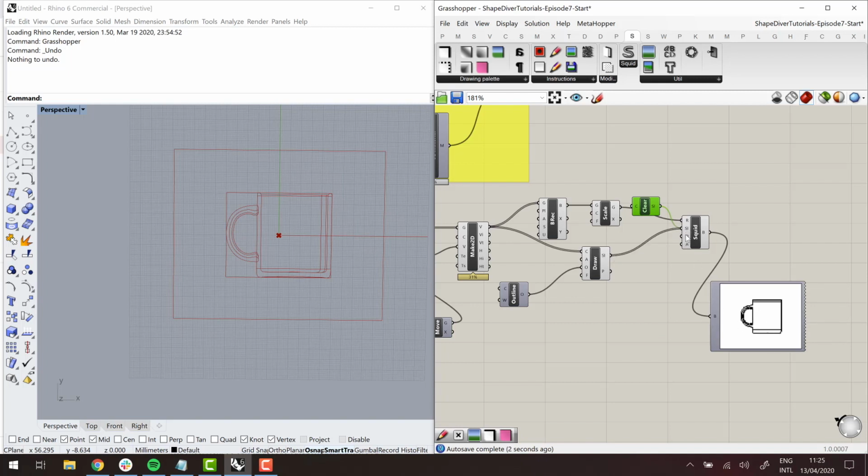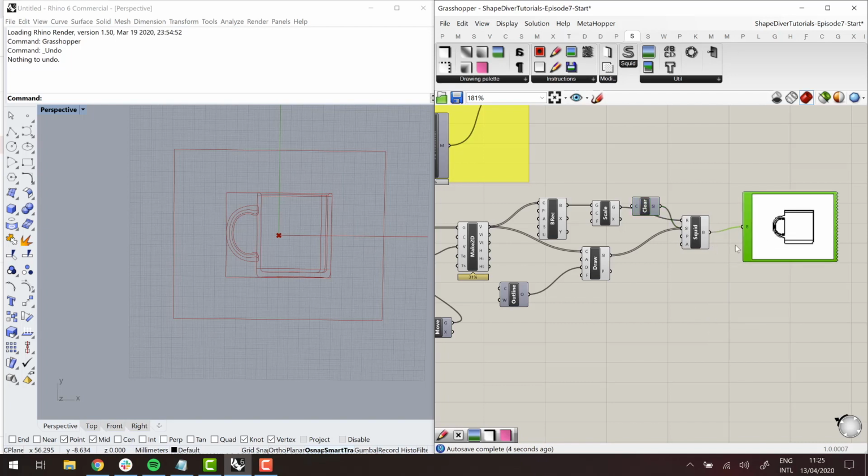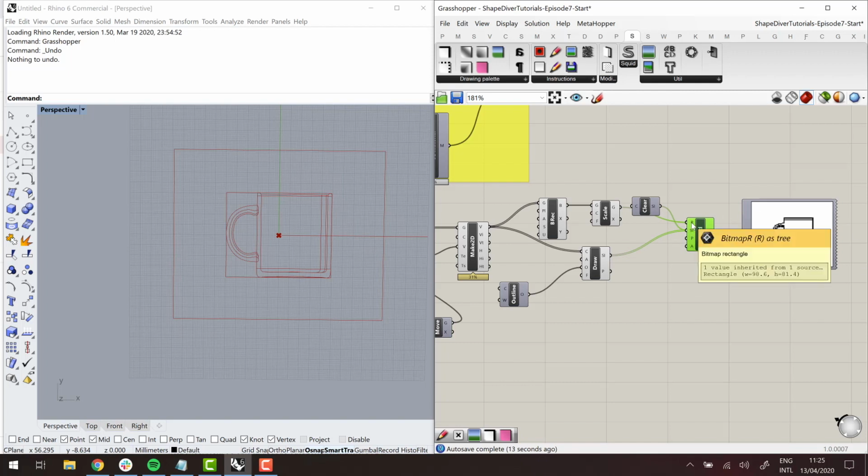And we have it. Here we can play with the parameter I did not mention yet, which is the pixels per unit. So the size of this bitmap here, by default, is going to correspond exactly to the input rectangle, well, up to the rounded integer. And so here I have an image that's 98 pixels times 81 pixels. Obviously, that's very small, and you can't have a lot of details. So if I play with the pixel per unit parameter, I can actually resize the image to have more pixels. So let's say I'm going to make an image 5 times bigger.